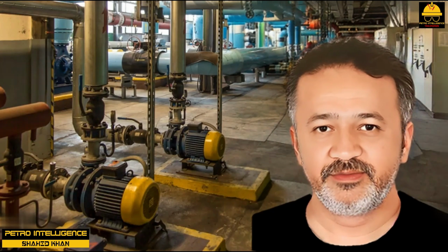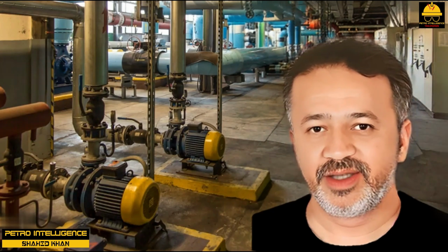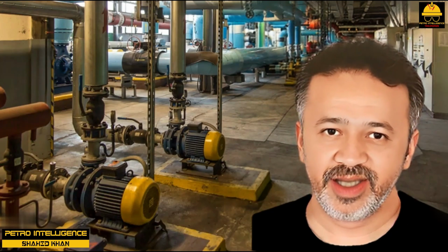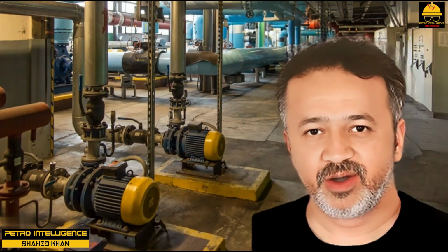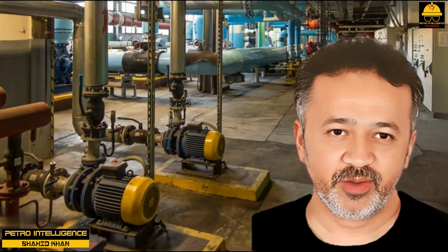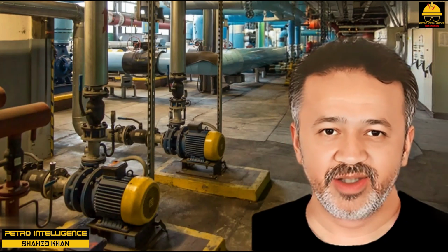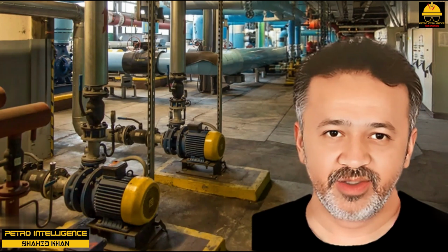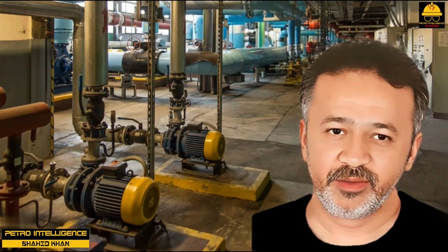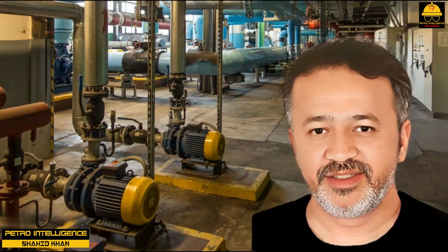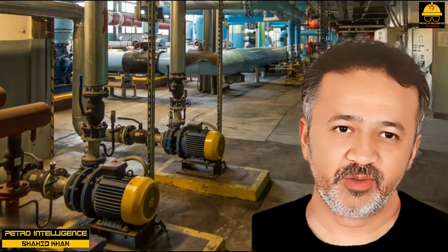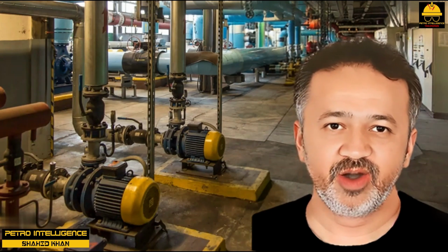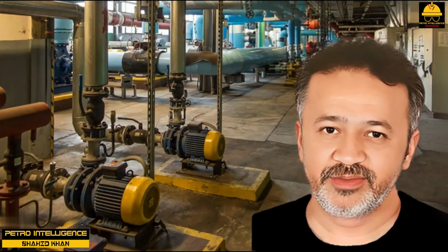Electric motors. Pumps are driven by either fixed speed or variable speed motors. Variable speed motors are becoming increasingly common. Flow can be controlled by varying the pump speed with the motor and thus eliminating parasitic energy losses across a flow control valve. However, because of the extra electronic components needed for a variable speed AC motor, 95% of the motors we work with are fixed speed alternating current motors. I will only discuss fixed speed, alternating current, AC, motors in this lecture.